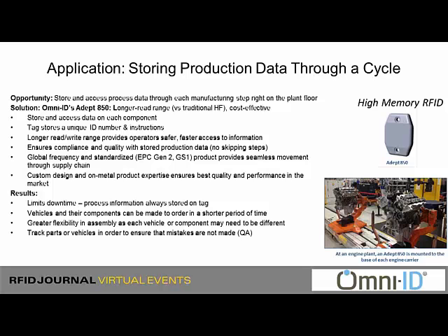And a PLC can check that tag at each station to make sure that the previous step has been done correctly, to make sure that this part is in the right place, and can again timestamp its operation so you get a complete record. For quality, this kind of birth history and as-built record is essential in understanding exactly how the product was built, if there was a recall or a safety issue related to that critical device.